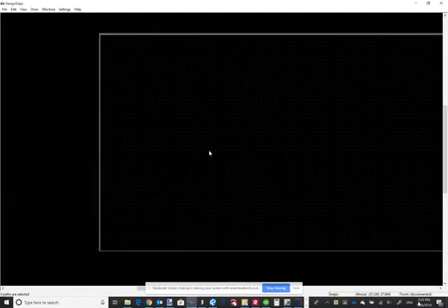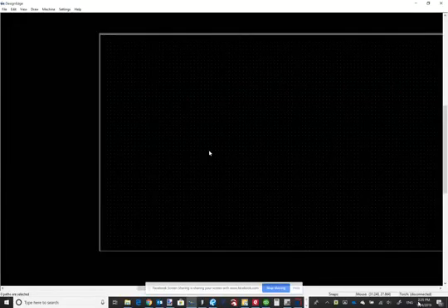Plus, to be quite honest, what it does is let you import paths that have 3D properties, but the ability of Design Edge to create good 3D tool paths for things like routing is just not there. So I use another program to create the tool paths, and then I import 3D paths as cut paths and run them. I don't know that what I would have to say about that would be very helpful to convince you it's worth it. But if you're going to do serious routing of detailed designs, then I use something like Vectric VCarve, and you still have to have the 3D upgrade in Design Edge to import those paths.